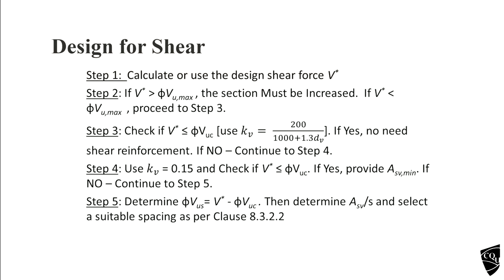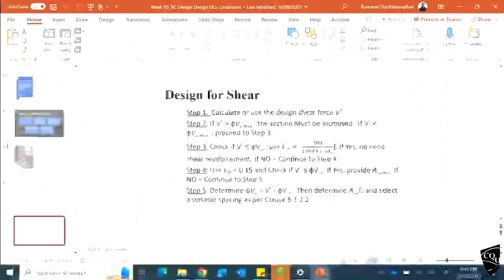So that's it, finished. Otherwise, we need to do the shear reinforcement design. That means you need to calculate VUS, and from that calculate ASV upon S, and we need to provide the shear reinforcement. So those are the steps.